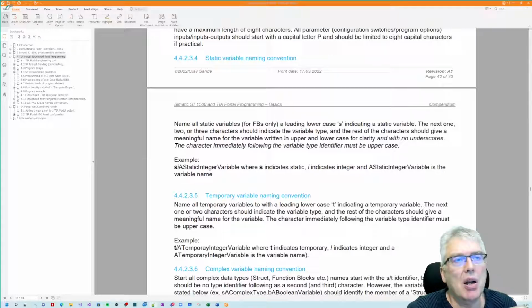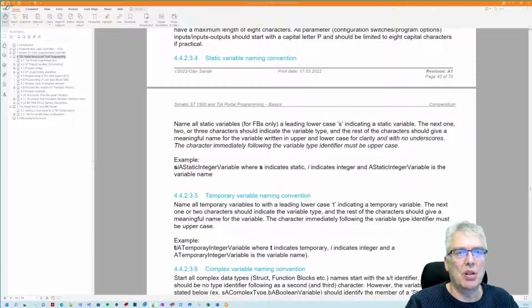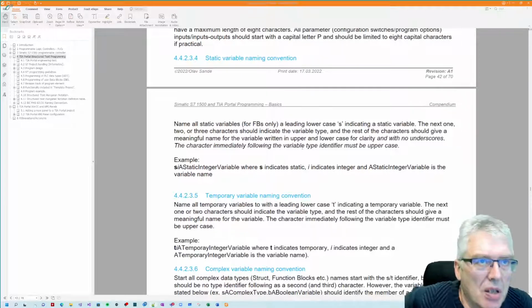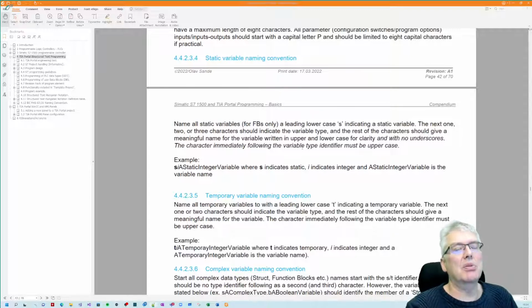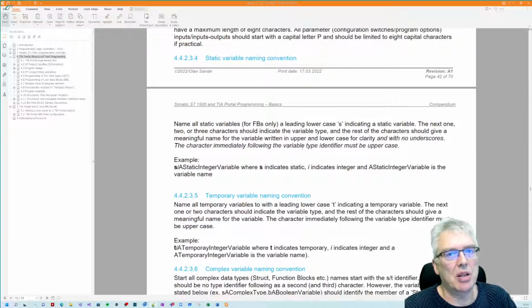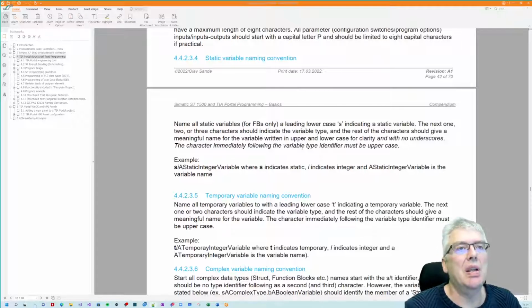There are inputs, outputs and in-outputs, but then you get inside, what is only visible to your program. The user can't see it. Now the user can see this, because the information hiding in TIA Portal is pretty poor. Static or internal data in a function block, you can access those from outside your function block, and that's not good. It shouldn't be like that, but that's the way it is.